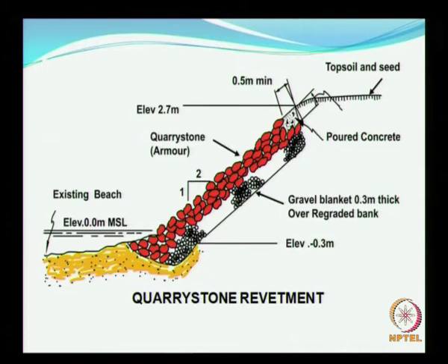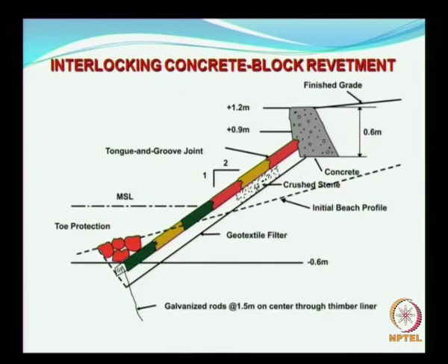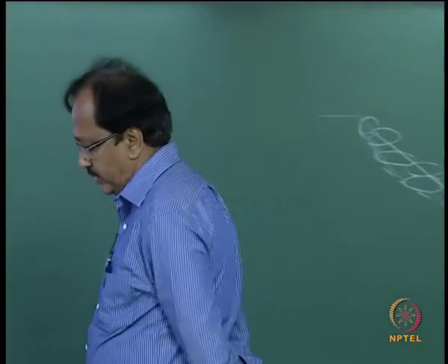The phenomenon is almost the same whether it is a sea wall or a revetment. So the same thing can happen if you have flooding in the river. You can have overtopping, and then you can have the removal of stone from the land side. So this has to be kept in mind. Every time, dumping of stones again is an eyesore.